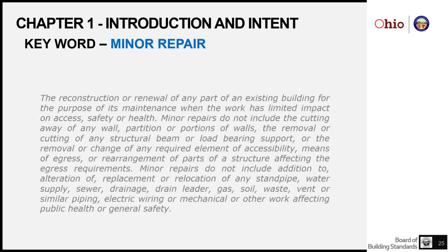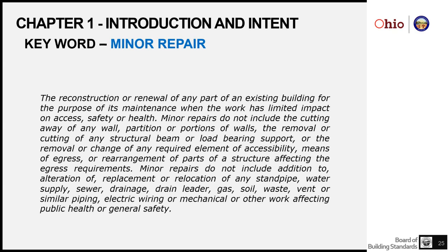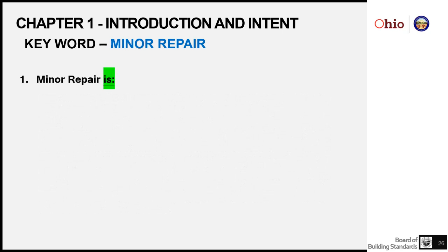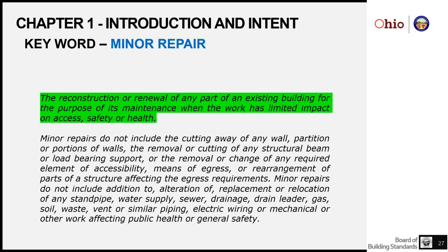Minor repair. This is the definition as it shows up. Minor repair, almost every contractor that I talk to on a daily basis would really love everything to be a minor repair, even the construction of a new house if they could figure out how to do it. This definition talks about what a minor repair is, as well as what a minor repair is not. So the first part is pretty straightforward. It's the reconstruction or renewal of any part of the existing building for purposes of its maintenance when the work has limited impact on access, safety, and health. That's what minor repair is.